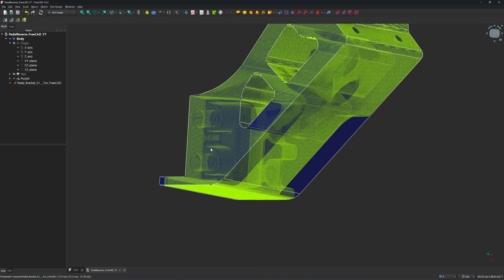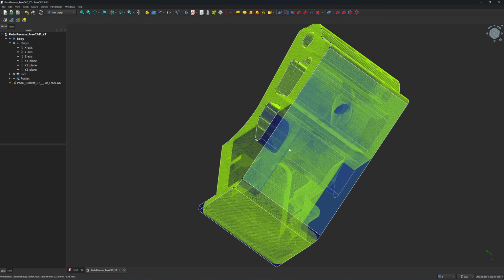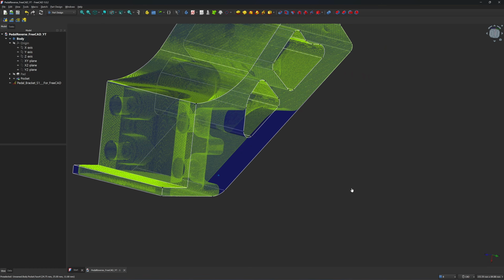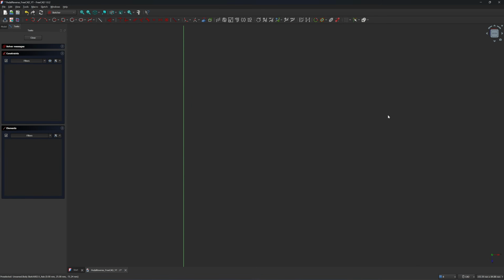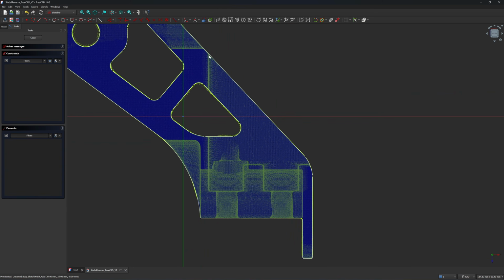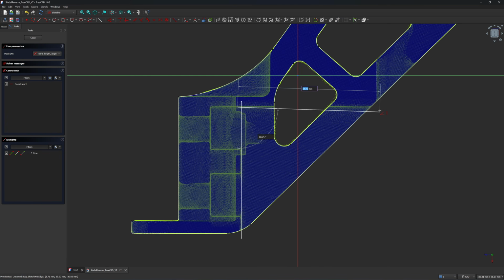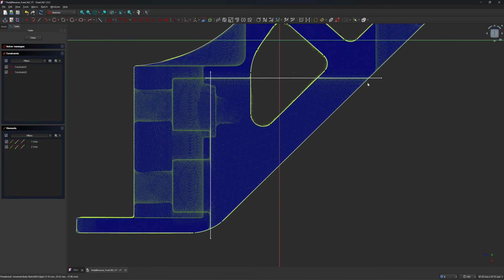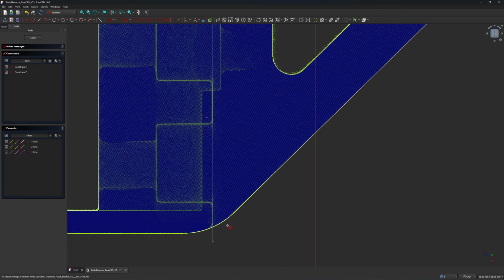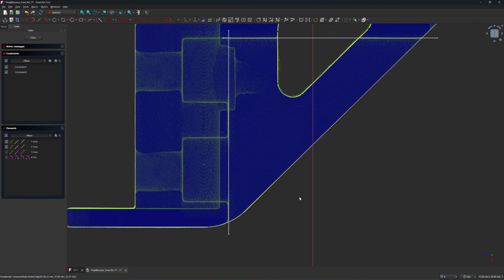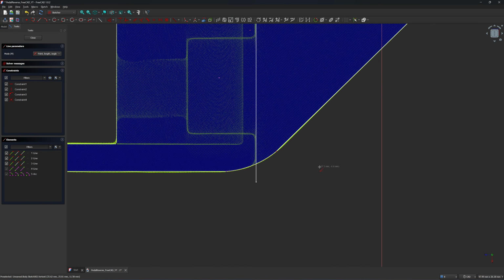Okay, next I'm going to make this pocket and cut it to here. Click on this face and click on the sketch. You can slice the graphic. I'm going to cut it from here to here and from here to here. And then I'm going to project this line. Right click, create external geometry. Draw a line using the reference.